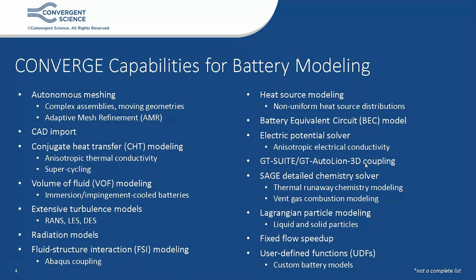Converge can also model fluid structure interaction simulations, and for more detailed simulations, including deformations, we can apply a co-simulation Abaqus coupling approach, for example, modeling battery swelling. Now, batteries generate heat during their normal operating conditions, so an appropriate heat source must be enabled in your simulation.